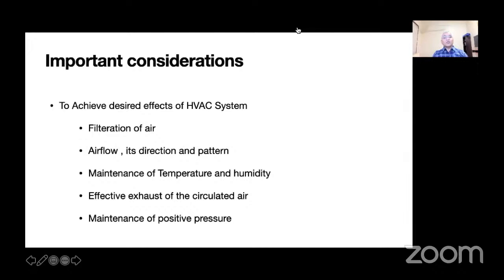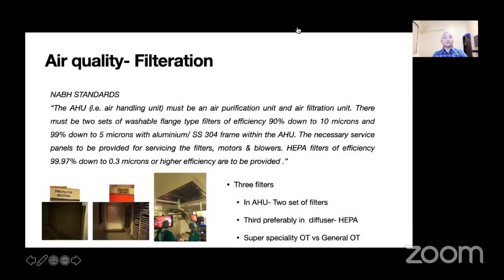Then it should provide proper airflow, which has to be unidirectional towards the operation theater table. Then you have to maintain temperature and humidity inside the operation room. There has to be effective exhaust of the circulated air. And then you have to maintain a positive pressure area so that surrounding air does not enter into the operation room.